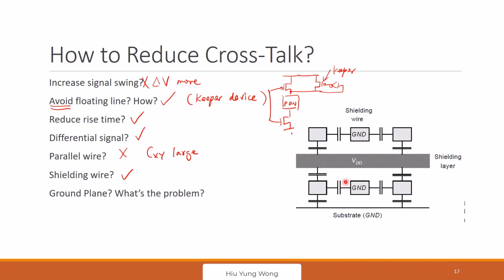Then the signal cannot go through, and I can avoid the crosstalk. Okay. And finally, of course, you can add a ground plane also, but you increase the capacitance, which means you increase the power, right? And you increase the area, which we don't want from the PPAC perspective.